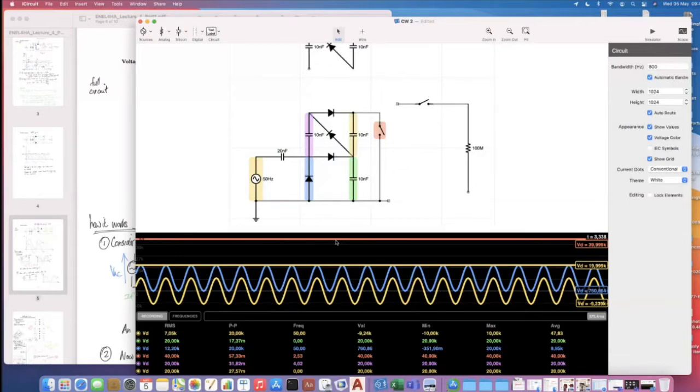If you look at the VD now, the red voltage, you can see that we've got a nice DC waveform. Got a nice DC voltage. That voltage is 40 kV. It's doubled from 20 kV. Right, so we've not only doubled the input voltage, the peak of the input voltage, but now we've multiplied it by 4. So we've doubled it again.